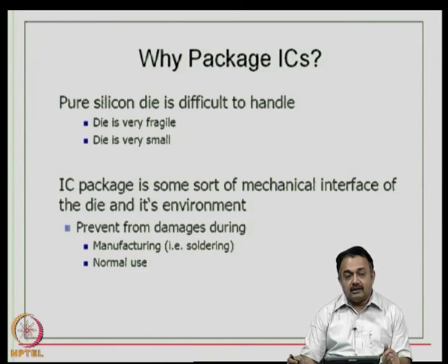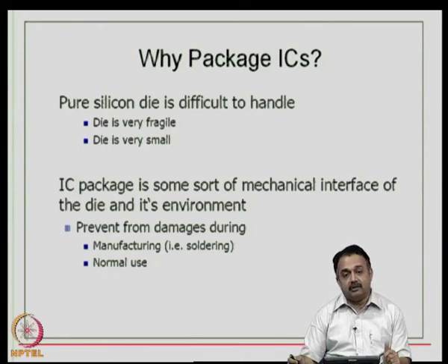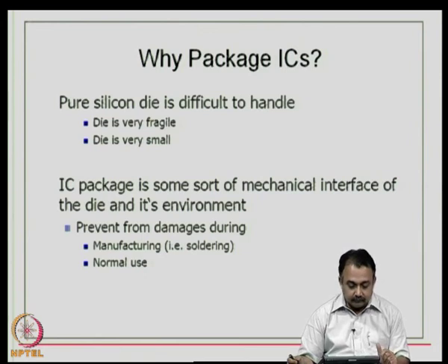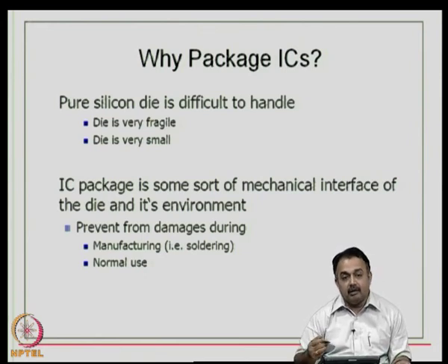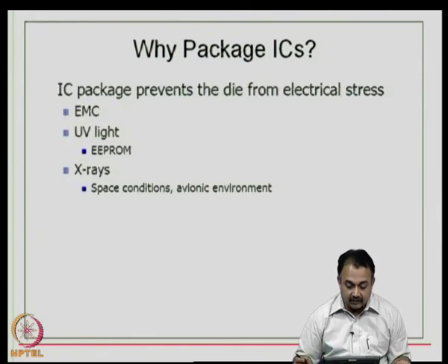So, it prevents damages during manufacturing, especially soldering, where a lot of heat will be involved and your first level interconnect cannot be disturbed or spoilt during the soldering process, which involves high temperatures, and also from normal day to day use after the device has been manufactured.